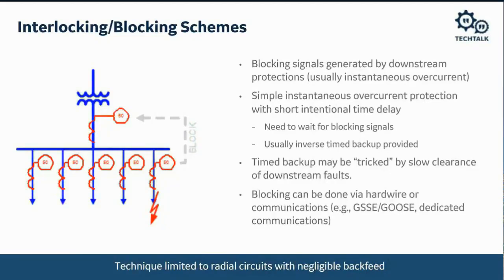The drawbacks of this scheme is the wiring. Obviously, we need to wire all of these signals back to our source relay. So there might be multiple wiring that we need to wire back, so terminations and all the wires that we need to run. The other thing is maintainability of this scheme. If we do have a break in one of those wires, there's an issue with one of those wires, we might not know about it until it's too late.